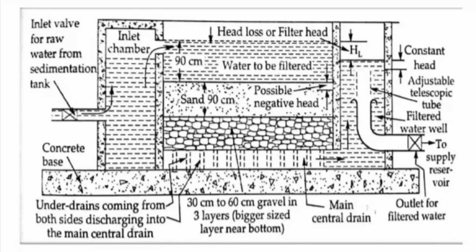This cleaning is done in such a way that the top layer of the sand media is scraped out using labor, and all the operations in the filtration tank will be stopped at that time. The top layer will be removed, washed, and replaced in the filtration chamber. This will take a minimum of 24 hours, and a large number of labor is required for this process.